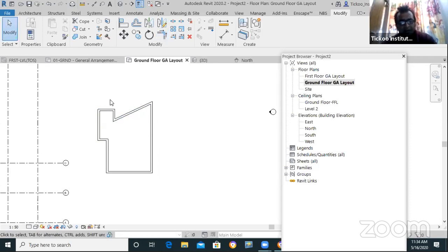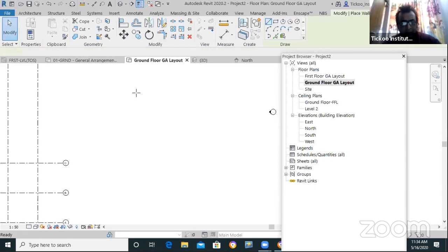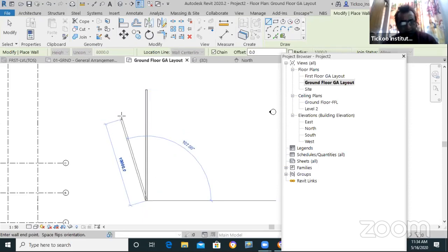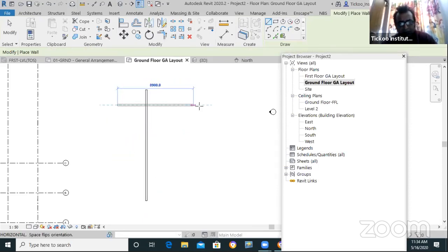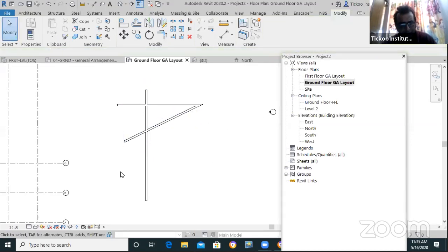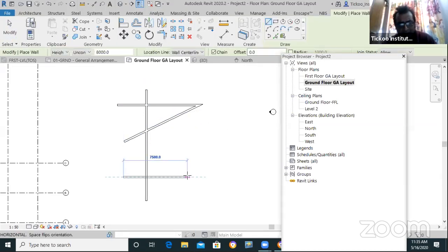Let us take another example. So I'm selecting it and let's say deleting it. So I have a wall. The shortcut for wall is WA. So let's create the wall first and let's say press escape. So you have this, right? You have the wall and you have this.